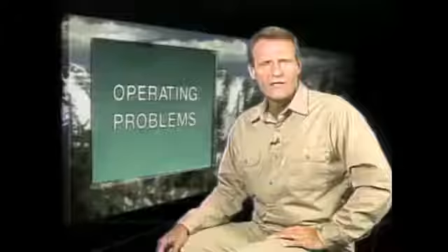Now, there may be other indicators you should check to ensure that a system is operating properly. For example, sight glasses on the receiver outlet can be used to check the flow of refrigerant. Ideally, a vapor compression refrigeration system will run efficiently and practically by itself. Sometimes, however, problems may occur. One of the more common problems that can affect a refrigeration system is an improper amount of refrigerant. The amount of refrigerant can be determined by checking a level indicator on the receiver or by checking a sight glass on the receiver outlet.